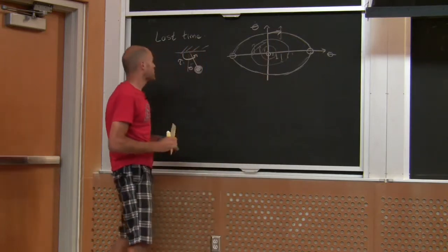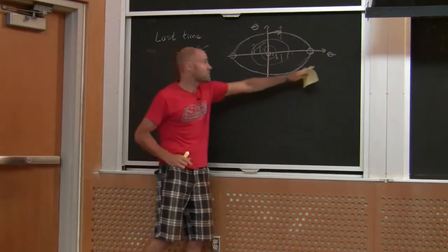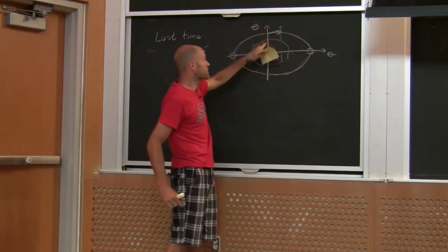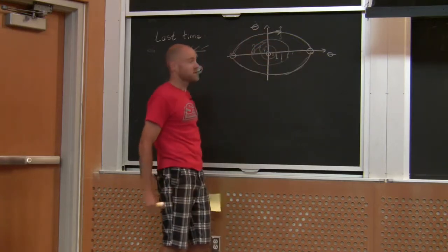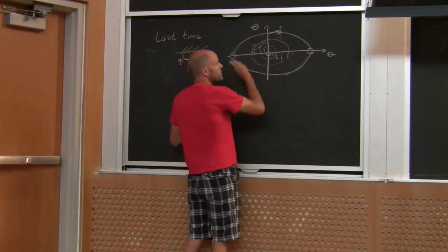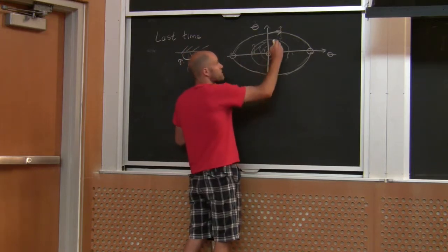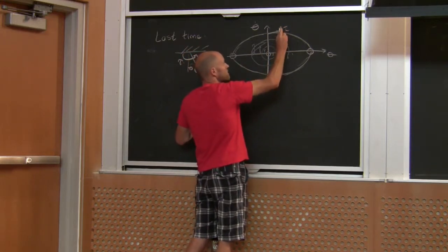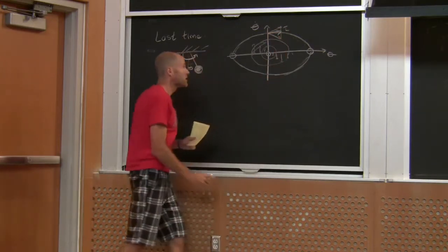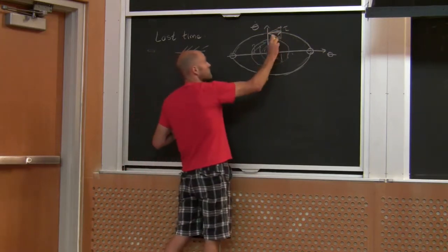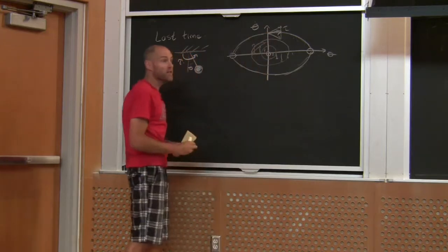If I made torque a function of theta and theta dot, I could selectively change the vector field everywhere in space. But the way that the torque enters, since it's a second order system, I could only affect the vectors in this direction. So I could tilt the vectors a bit, but I can't somehow make them go backwards in velocity or anything like that.